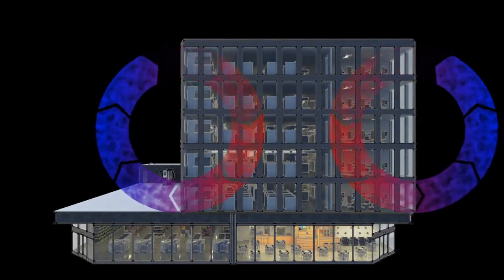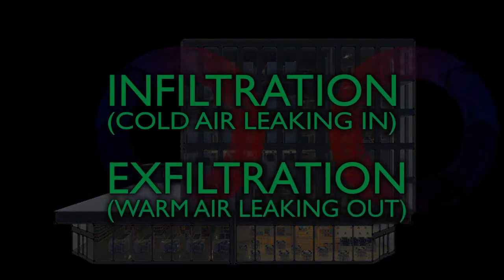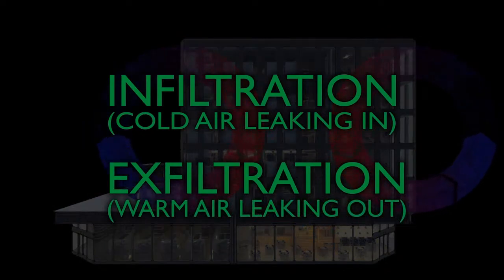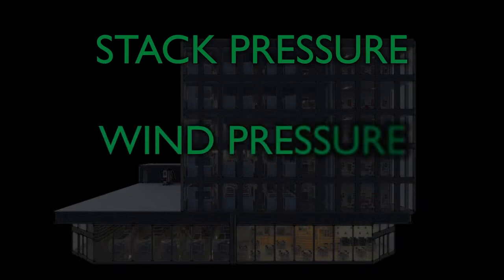The 2 basic factors affecting air movement are infiltration and exfiltration, air moving in and air moving out of the envelope, and there are various mechanisms which drive this. The 3 main air pressure phenomena affecting air movement are stack pressure, wind pressure, and mechanical pressure.